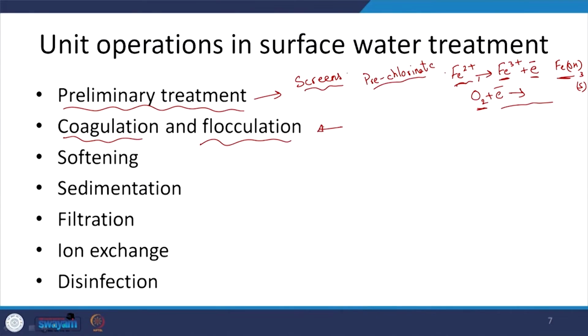First we will understand why, and then we will see how we can address this issue through coagulation, when we destabilize the solution. So, in coagulation, I am adding coagulants to destabilize the system so that the initial coalescence can take place. Initially the particles can start coalescing, or I want to be able to neutralize the charge on the colloids. Again we will see why, and then after this we want to promote formation of bigger flocs. Flocs we also came across in wastewater secondary treatment. After biological treatment, the kind of microbes we want to form, they will settle down, right. So, that is something we looked at. Over the next 2 or 3 lectures, we will be looking at coagulation and flocculation.